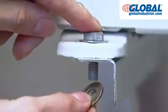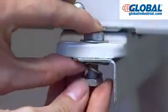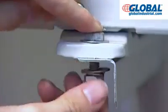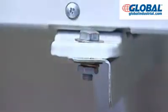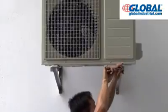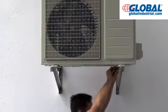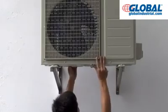Align the elliptical hole of the foundation bolt with the fastener hole of the bracket. The outdoor unit is fixed on the bracket by 4 bolts. The bolt is threaded from up to down and is tightened by adding a check washer. If allowed, a rubber gasket can be added to reduce the vibration of the outdoor unit during operation.